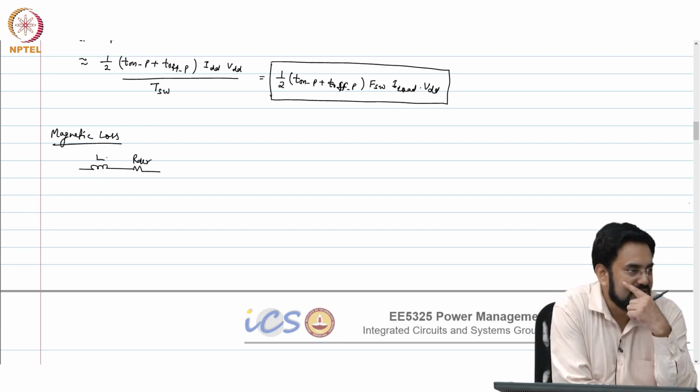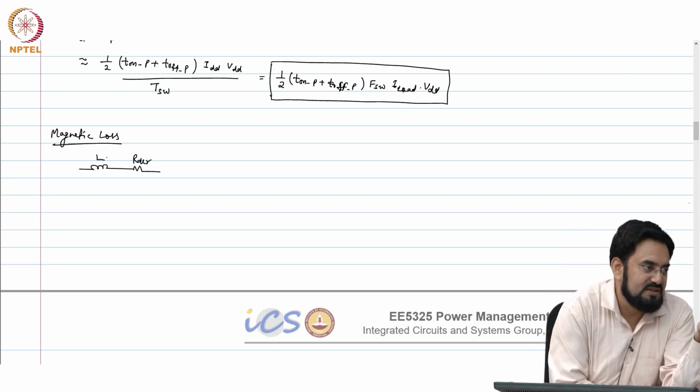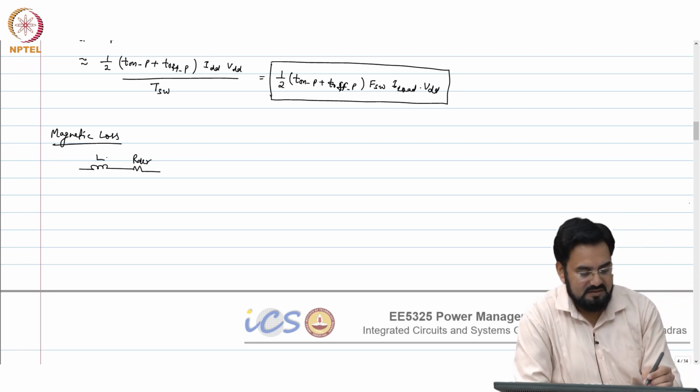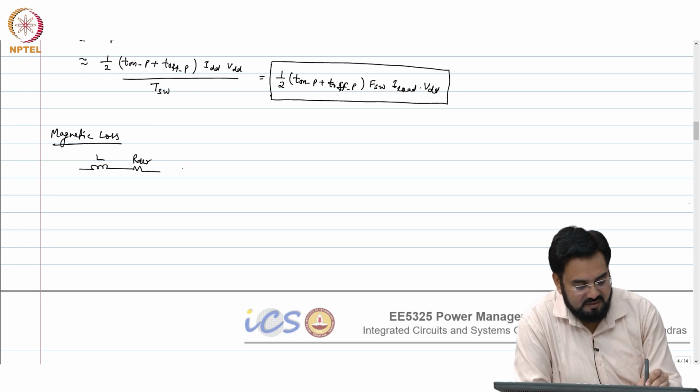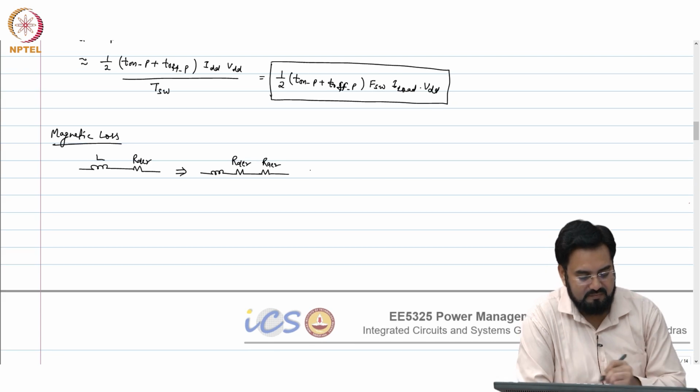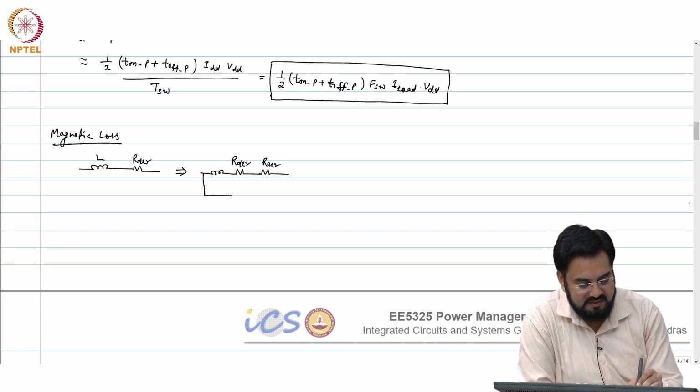this is here, but in reality this is not true actually. This is for a DC model, but if you look at an AC model, then this will have one more resistance. And it will have a parasitic capacitor also, Cp.